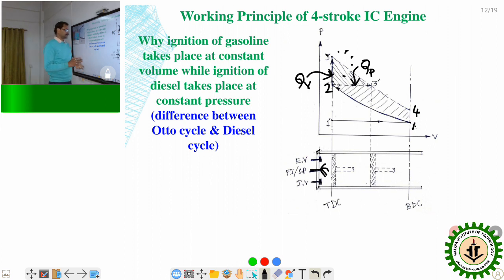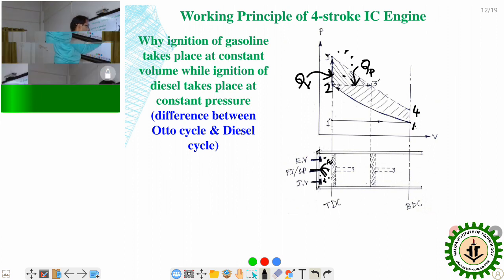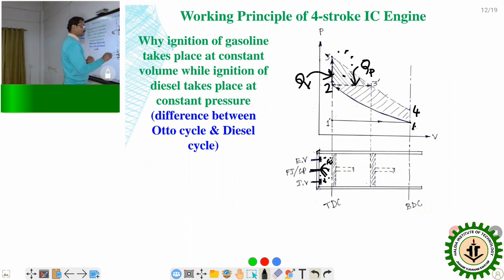Within this temperature, diesel will start igniting at various points, but not the whole diesel. Again, the diesel around this point will start to burn. Again, the diesel around that layer will start burning. So the burning of the whole diesel within this clearance volume will take some time.